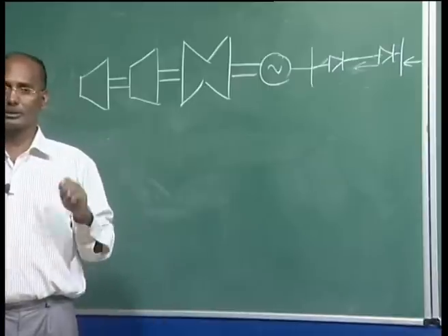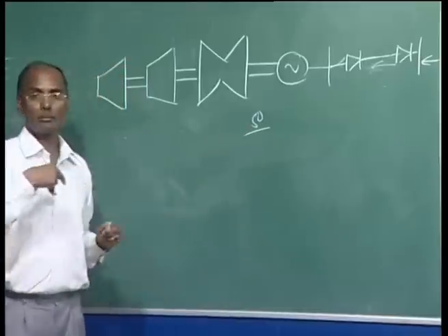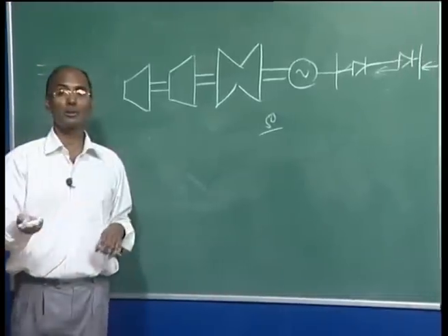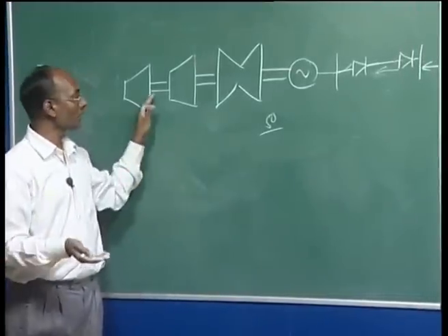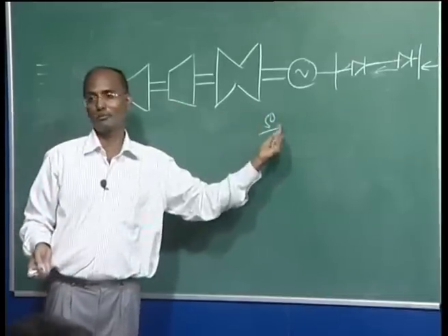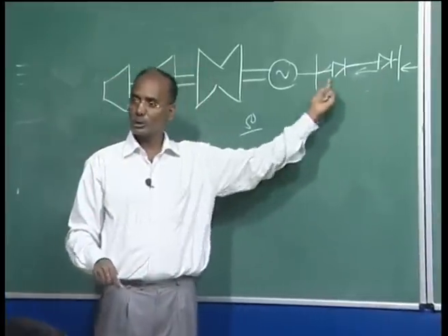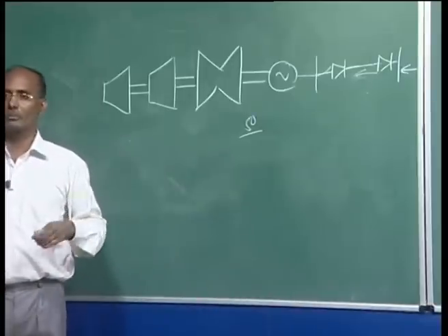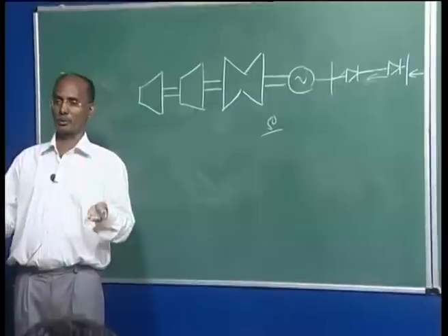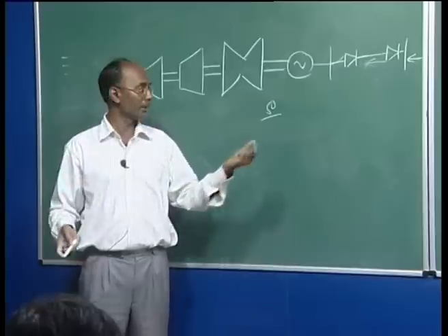You know the SSR problem is subsynchronous, meaning the frequency is less than 50 hertz. But I am sure people have not heard of supersynchronous resonance, because the machines are designed in such a way that the critical frequency is always less than 50 hertz. So even though higher frequencies are entering here, they will not bring in this torsional oscillation concept. We never bother about the supersynchronous. If the frequency is more than 50 hertz, that is a multiple of frequency, inter-harmonics and integer harmonics.